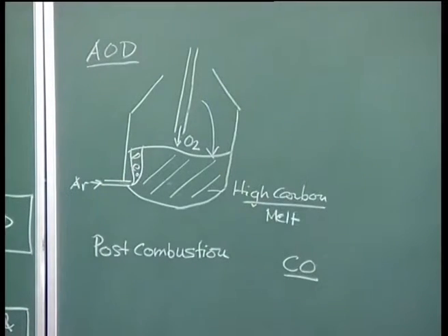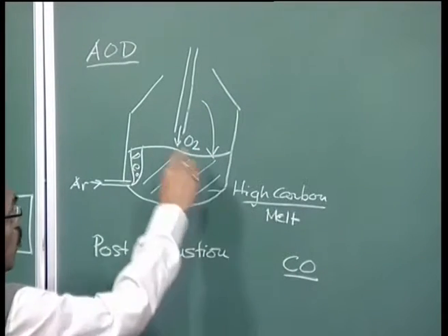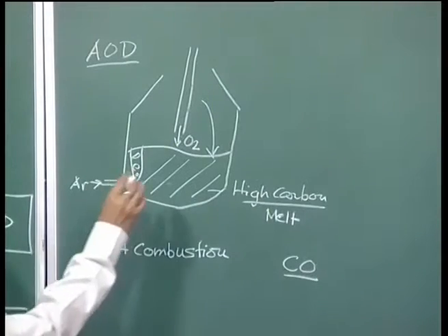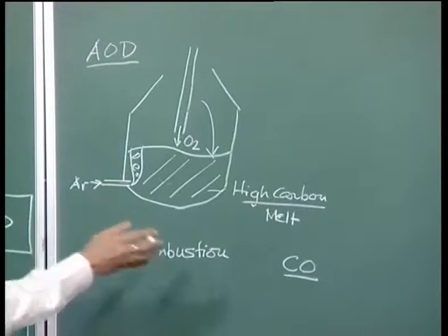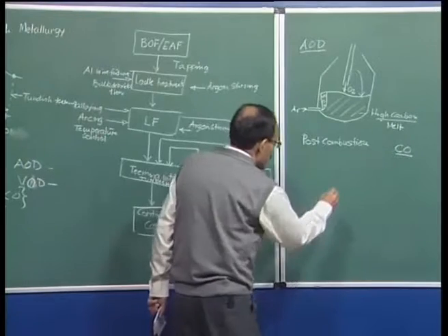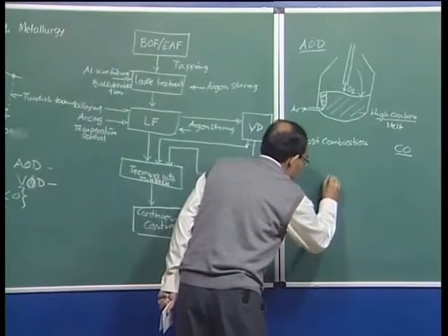We must understand that post combustion is going to be meaningful towards the beginning, the initial part of the blowing, when there is a lot of carbon monoxide evolution and the carbon concentration is very, very large. The VOD process is similar to, we have a ladle here.